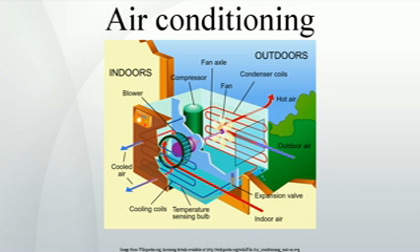Modern units might have a coefficient of performance, COP, sometimes called efficiency, of approximately 3, that is, 1 kilowatt of electricity will produce 3 kilowatts of cooling. A dual-duct unit draws air to cool its condenser from outside instead of from inside the room, and thus is more effective than most single-duct units.